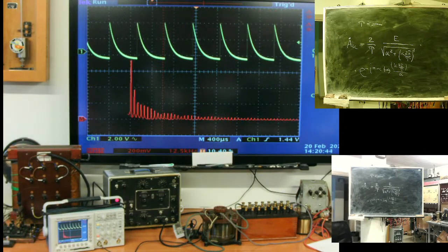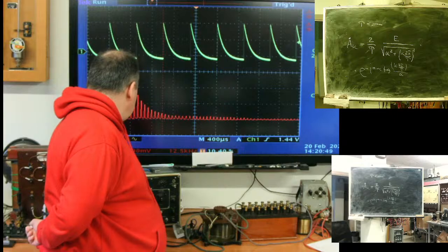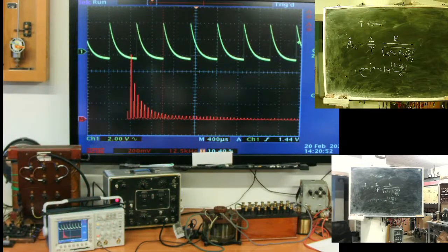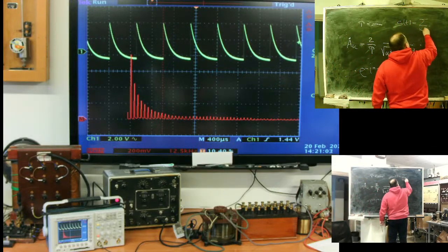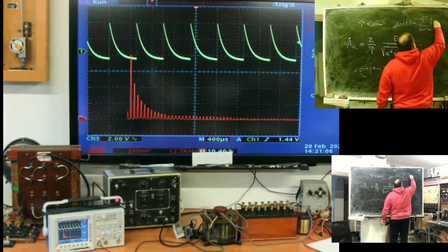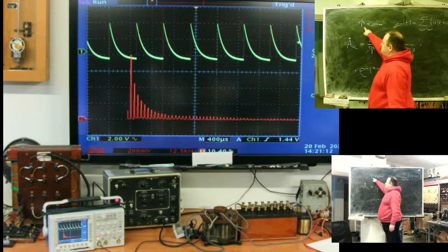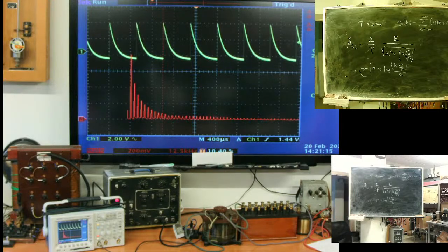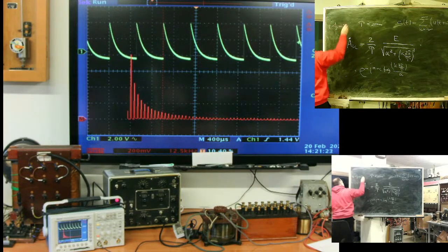Yeah, now my scope is performing a discrete time Fourier transform on my signal. Yellow is a sequence with this period. At this moment, half a millisecond. Frequency is 2 kilohertz, so no, 1/2 of a millisecond.